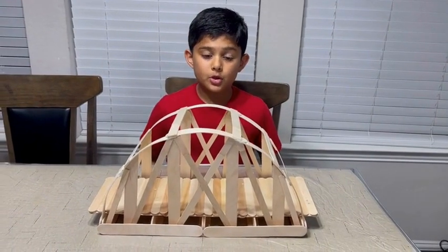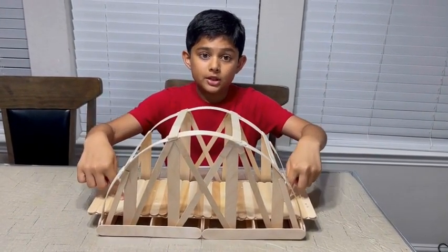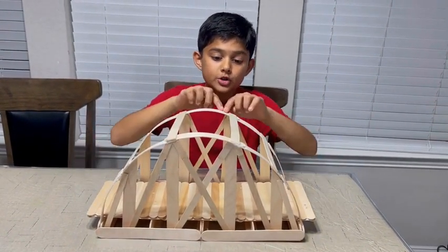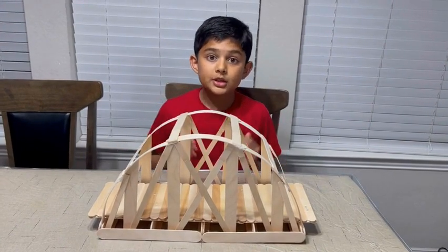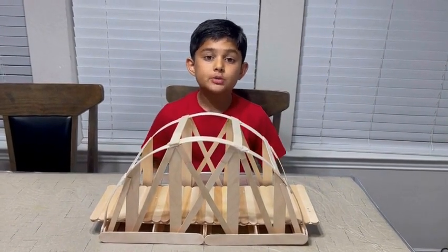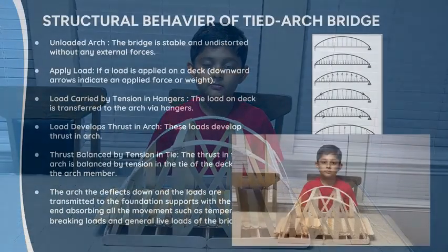What is the behavior of the bridge? When the load is applied to the deck, it is transferred to the arch via hangers. This creates thrust in the arch, which is balanced by tension in the tie beam.